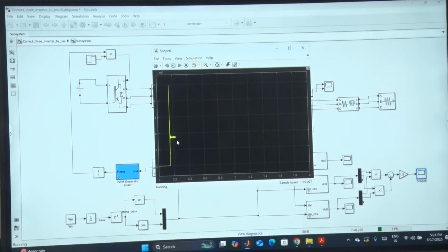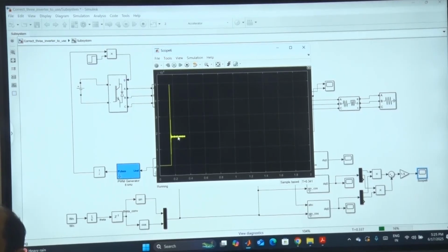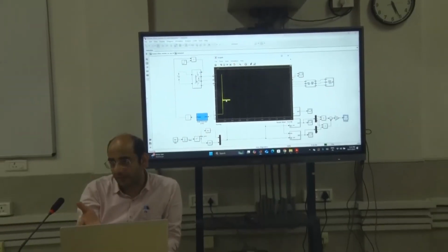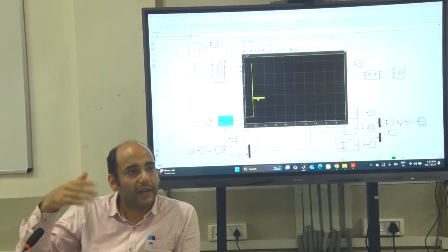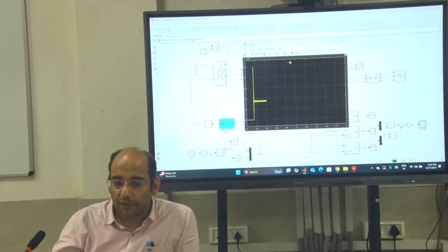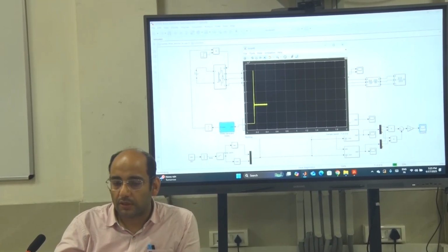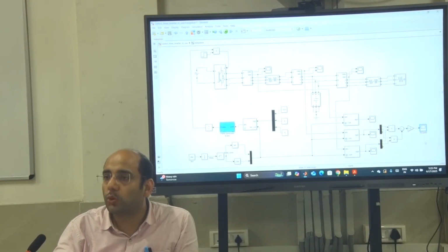Okay. Now to remove these ripples in the control design, what do we do? We put a filter. And you saw the instability problem? That is actually due to the filter, because a low pass filter always introduces a lag. A lag makes our control slow. That leads to instability. So if we have to plot the filtered one, I'll pass this calculation through a filter.